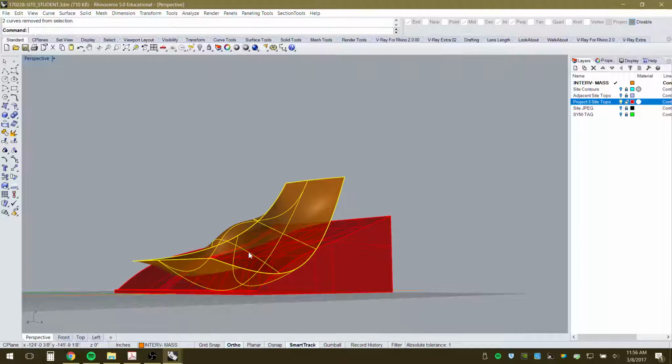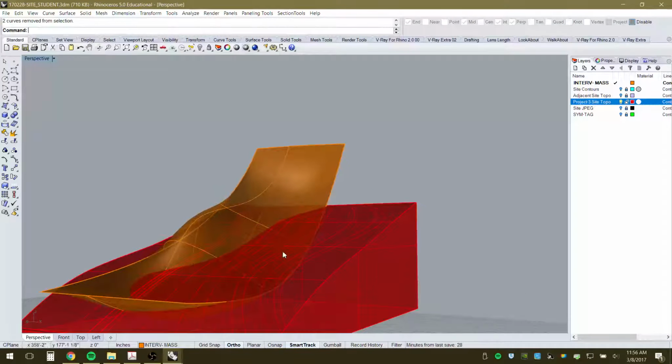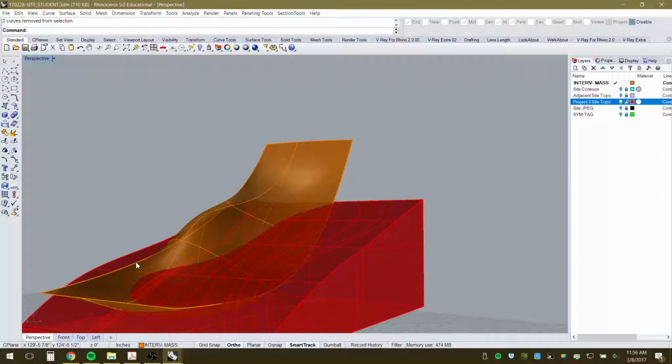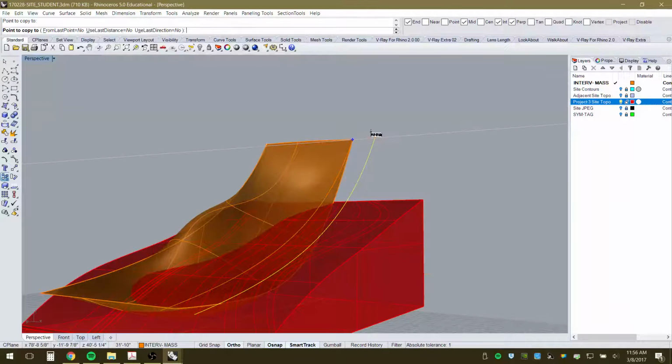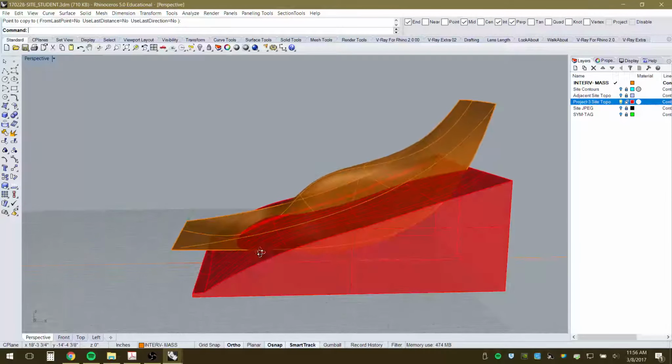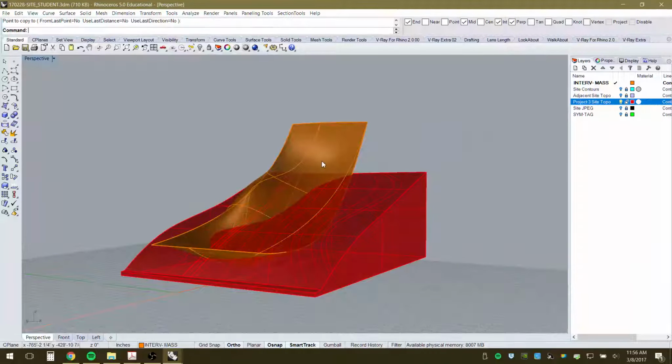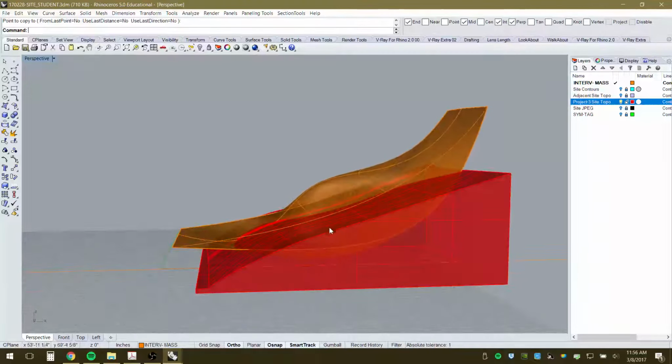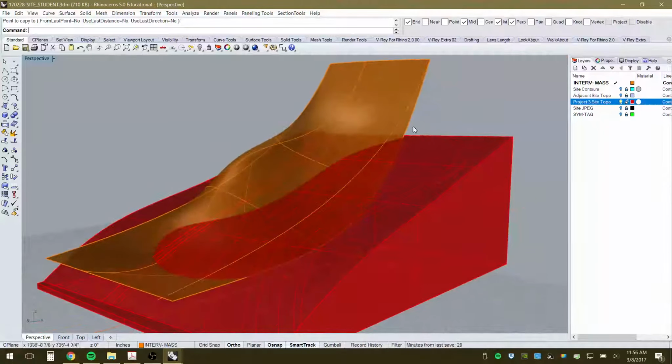So in order to kind of alleviate this as well, another way to deal with that is I could recreate the surface. So instead of lofting it the way I did, I could have maybe taken this curve, copied it over, turn my object snap back on here to there. And so I could create another sort of top edge, so I can loft from here to this one in the middle to now this one that I know is above the topography, and then this would be a kind of a flatter edge, and that could open to the exterior. Maybe that's what I'll do actually for this.